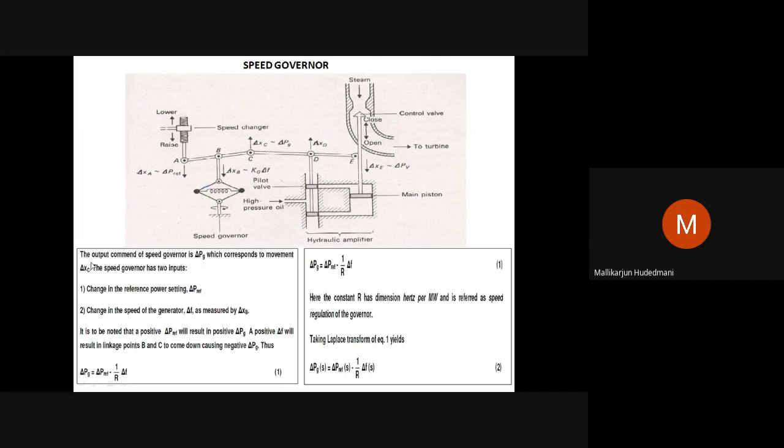For that we have the output of the governor, which is rotating continuously by the fly ball mechanism. This is going to change the displacement of points A, B, C, D, E. These are the displacements I was picking. Whatever set point you have set, how will that set point make this governor open and close for a change in RPM or change in load?